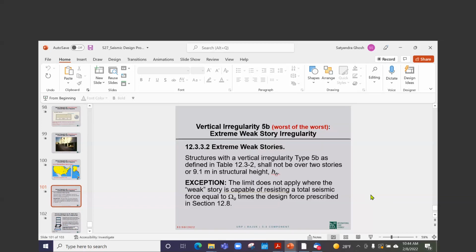If you ignore the limit of C sub u T sub a, you are further decreasing the stiffness of your building. If you decrease stiffness, you'll be calculating larger drifts, and the code has no problem with it. You are shooting yourself in the foot.